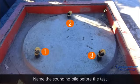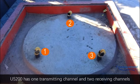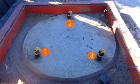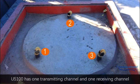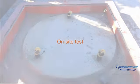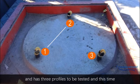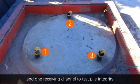Name the sounding pipe before the test and measure the clear spacing of the outer wall of the sounding pipe. U5200 has one transmitting channel and two receiving channels. U5100 has one transmitting channel and one receiving channel and can test only one profile at one time. On-site test. The pile to be tested has 3 sounding pipes and has 3 profiles to be tested. This time, we use one transmitting channel and one receiving channel to test the pile integrity.